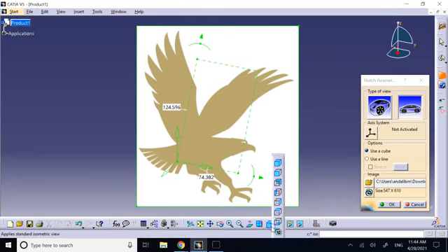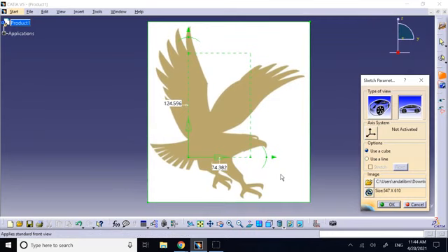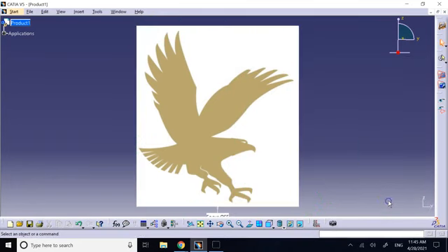So I go to the views and first make sure I'm seeing it in the front view. I align the axes and make sure the shading is shading with material, not shading with edges or without edges. It should be shading with material, this one. Then before I click OK, I make sure I put my origin and extend my axis such that this window in green, which you can see with dash lines, will contain my entire sketch like that. And now that I'm good, I say OK.